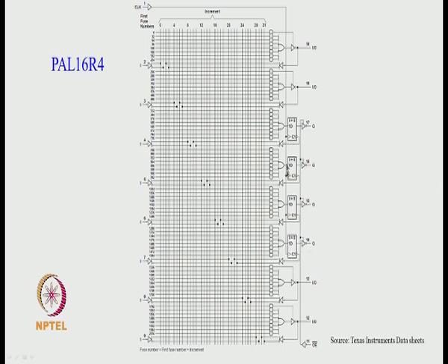But the important thing to note is that you have combinational logic followed by the flip flop, that means a register, and you see the Q bar of the flip flop is going back to this logic section as input to the AND gate. Now that tells you that if you imagine a counter, in a counter architecture we have seen we have a next state logic which decodes the present state, and in a complex counter you will have various inputs like up, down, load and all that.